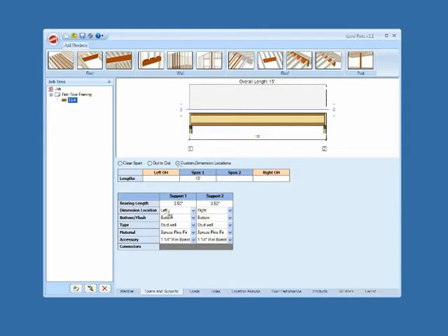If you choose custom, then you can specify down here in the grid what you're dimensioning to. So looking at our little example here, we have a 2-foot overhang and a 16-foot span, and that goes from the outside there to the center on this side.